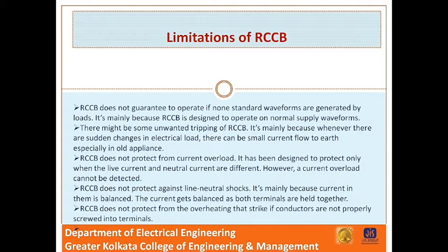It has been designed to protect only when the live current and neutral current are different. However, a current overload cannot be detected. RCCB does not protect against line neutral shocks, mainly because the current in them is balanced. The current gets balanced as both terminals are held, and RCCB does not protect against the overheating that occurs if conductors are not properly screwed into the terminals.